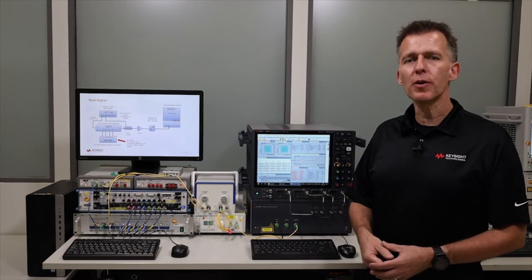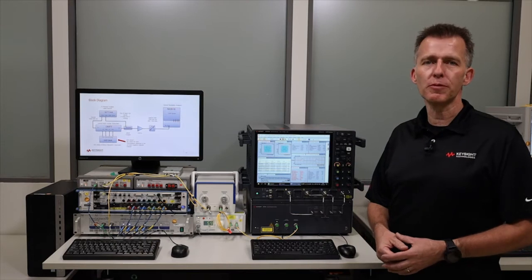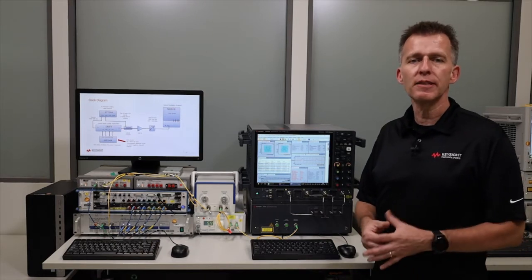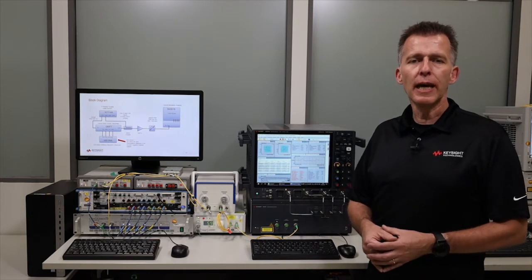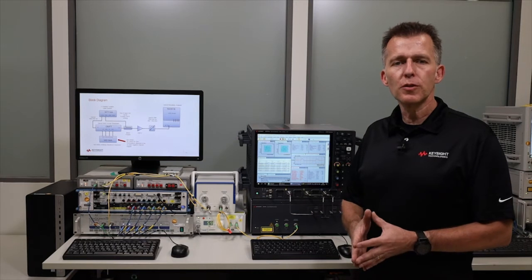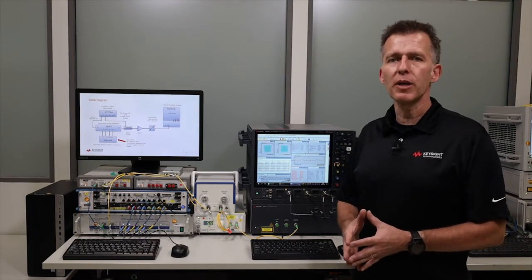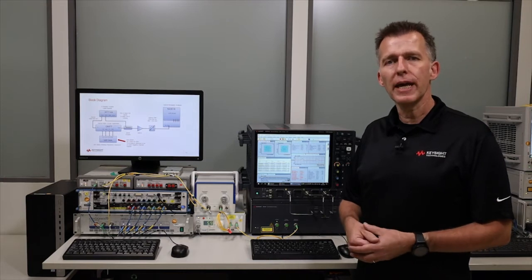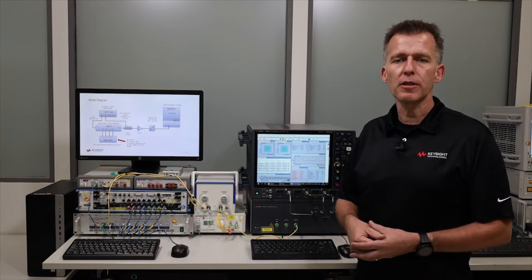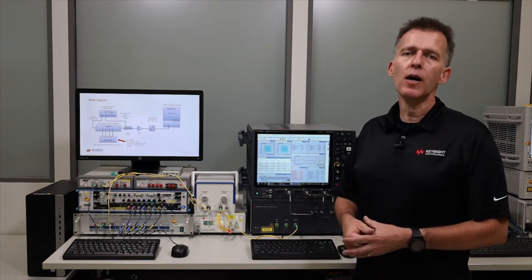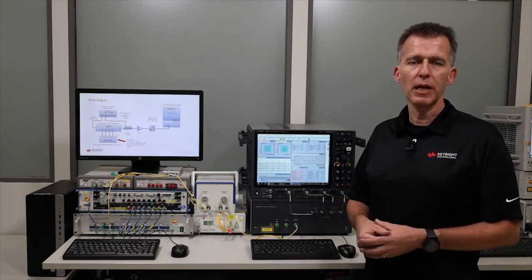Today I'm going to show you our solution for Coherent Terabit research, which is based on our lowest noise, up to 110 gigahertz OMA system and the industry's fastest arbitrary waveform generator. This allows you to test QAM even beyond 100 gigabaud. The products that are involved are our 8190 series of arbitrary waveform generators and the N4391D optical modulation analyzer family.